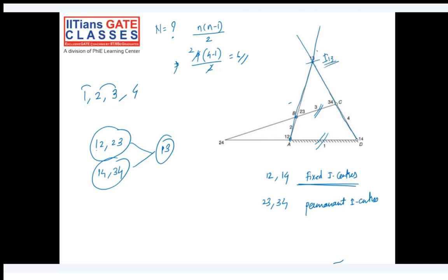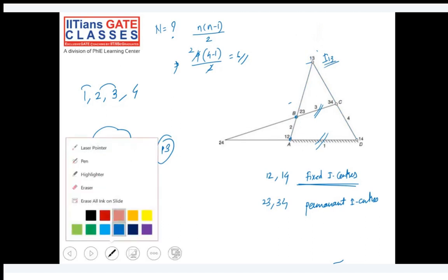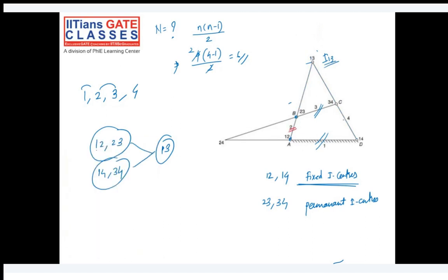In the same way, whenever we want to get the center 2 4, this is link number 2 and this is link number 4. The 2 4 center will get created after joining these two lines. It's just extending the line. Wherever it cuts, that particular point is your instantaneous center of rotation of links 2 and 4. The meaning of this is both links 2 and 4 are assumed to be rotated at this particular instant about this center of rotation.